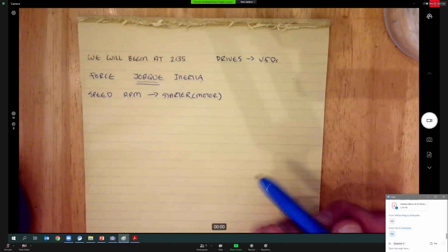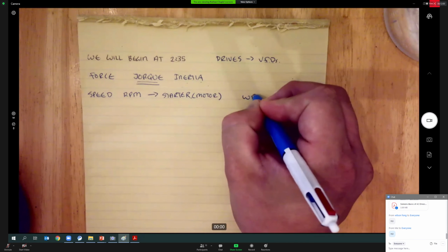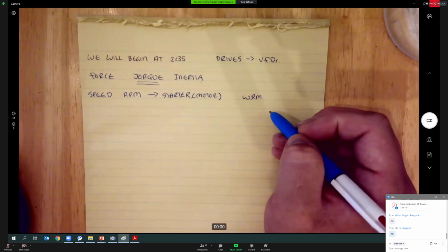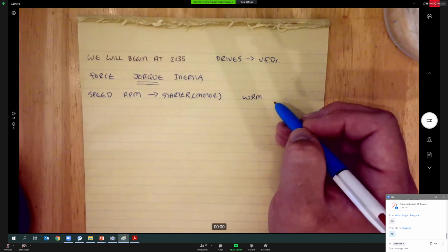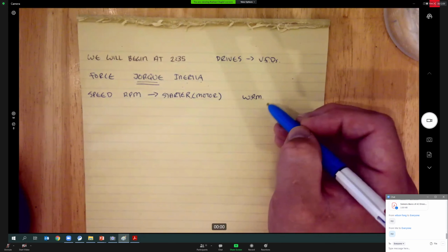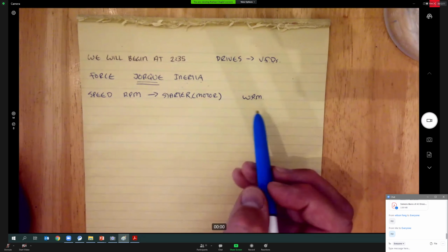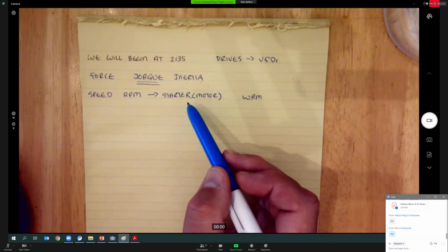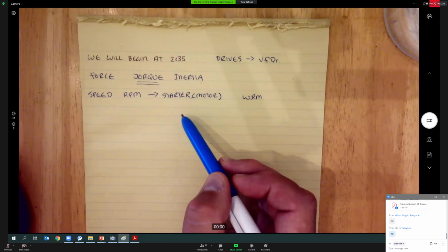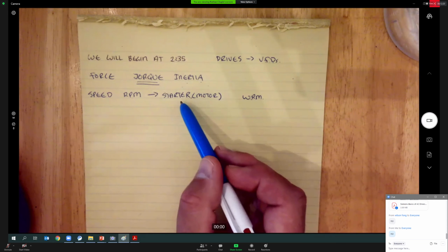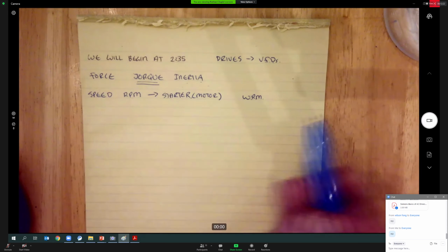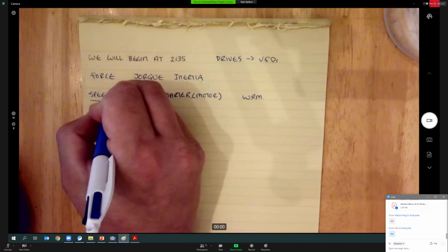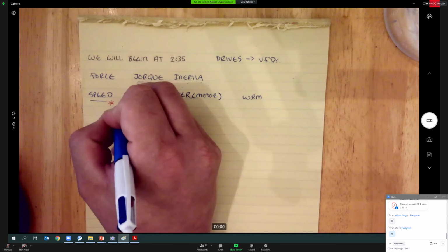We could be talking about a wound rotor motor where we have access to the secondary windings and we can control the torque at startup, which can control the amount of time it takes for a motor to start, but it's not speed control. So a variable frequency drive, one of the big benefits that it has over any other type of starter is that a variable frequency drive can control the speed, the operating speed of a motor.